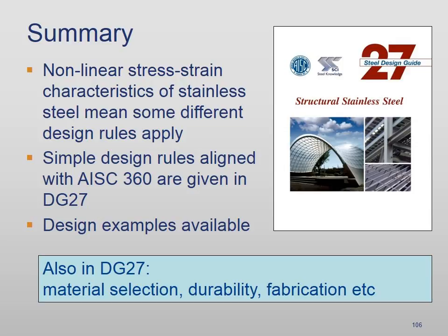I think Catherine can correct me if I'm wrong, but if it's dual certified, it tends to be certified to the higher strengths that relate to 304. Would you like to comment, Catherine? If it's dual certified, then actually you would have to go with the lower strength per ASTM, unfortunately. Because it is whatever is lower.